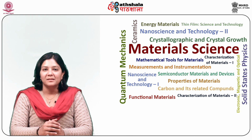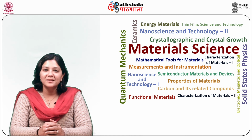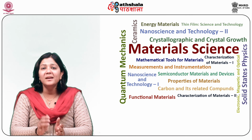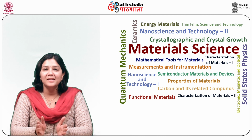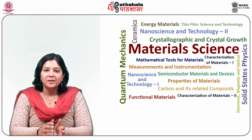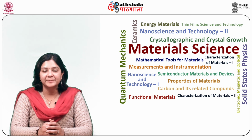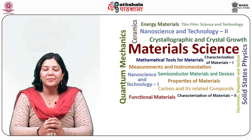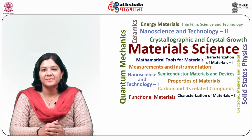Van der Pauw method. The Van der Pauw technique is employed to determine resistivity and Hall coefficient of a material. It can accurately measure the sample's properties for any shape if the sample is two-dimensional, solid, without holes, and electrodes positioned on its perimeter. It uses a 4-point probe positioned around the perimeter of the sample rather than in a straight line.